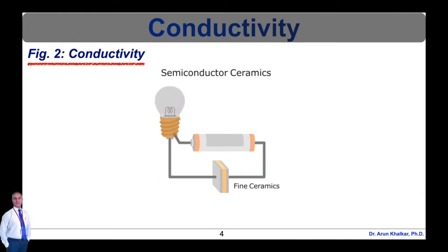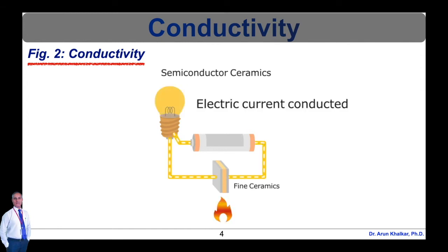These devices are used in sensors that monitor temperature changes and in equipment designed to prevent electronics from overheating. A varistor is a similar component that possesses a property in which resistance decreases as voltage increases. Varistors are used to protect electronic circuits from excessive voltages.